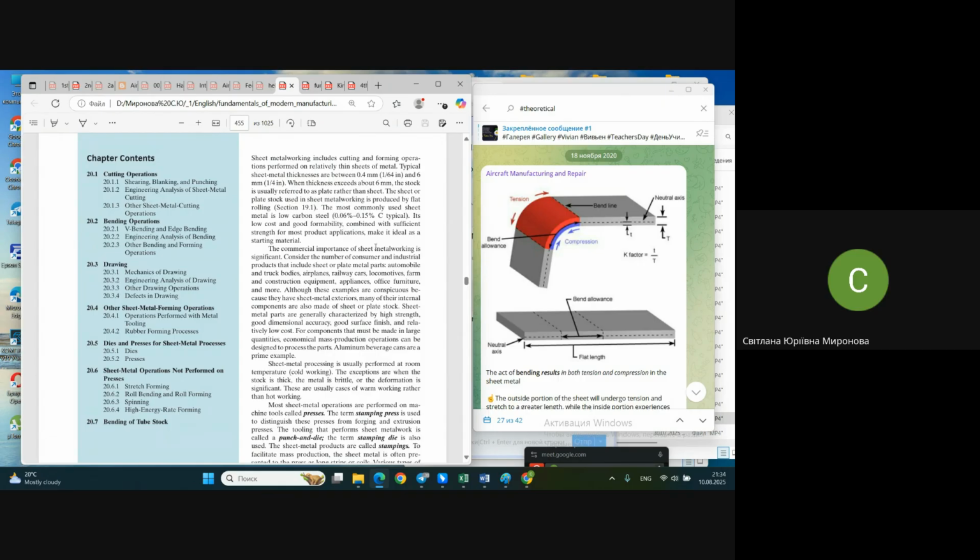But for bending operations, and especially when it comes to forming a huge surface, like stretch forming, for instance, of course, the spring back effect is significant and extremely unpleasant. And when it's a simple shape, like you just make a corner, it's possible to solve the problem by preliminarily increasing the angle of bending. If it's necessary to bend a straight angle, you bend it more. And after, it springs back to the value that you preliminarily bent more already. But when it comes to complex surfaces, when it comes to huge sizes, this approach doesn't work.